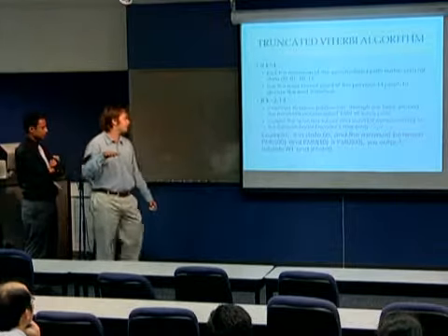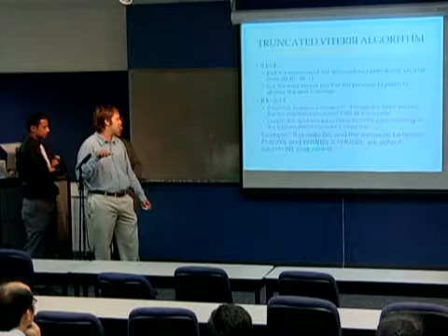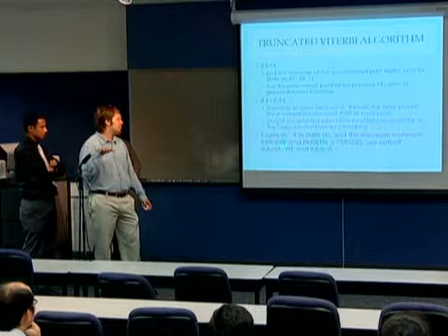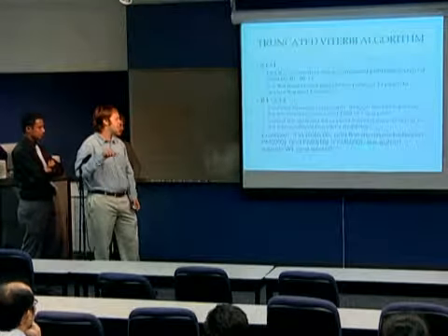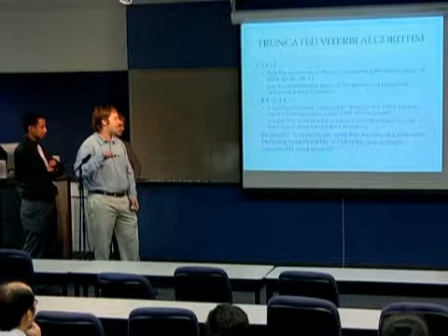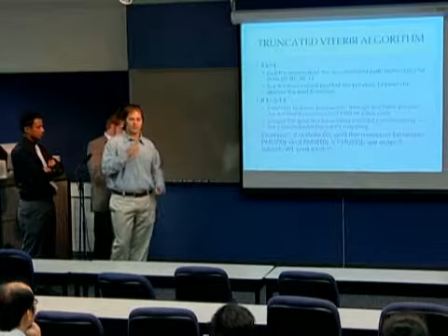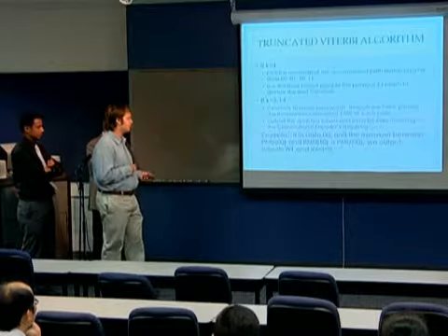So here's my example. If in state 0, 0, the minimum between PMU is, these are previous, so we're going backwards. If this is the minimum, we output subset W1 and input bit 0, because that's the reverse operation of the convolutional encoder.